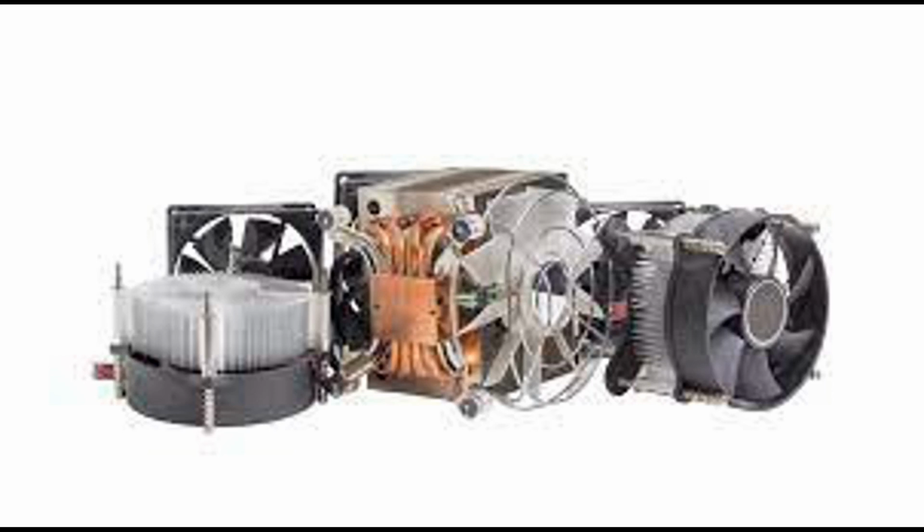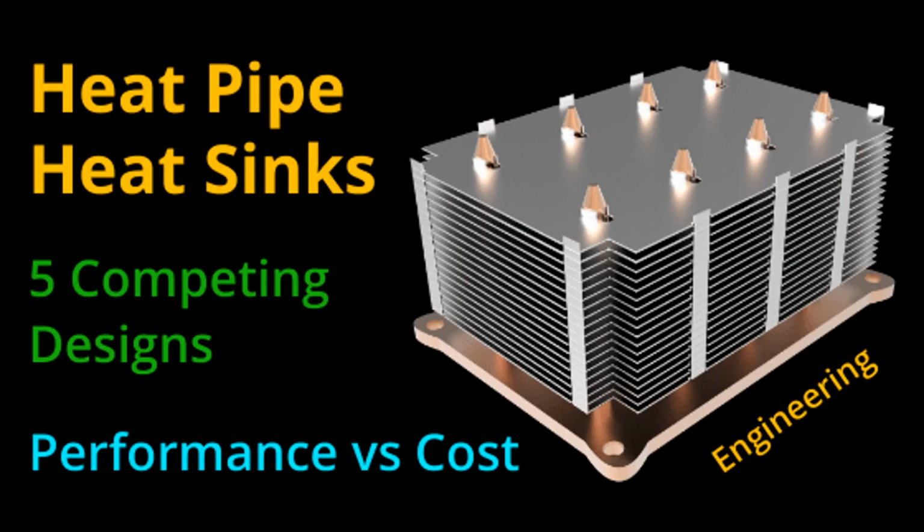Zigzag fin heat sink. Utilizes fins arranged in a zigzag pattern to increase surface area while maintaining structural integrity. This design is often used in compact electronic devices where space is limited. Swirl fin heat sink. Incorporates fins with a spiral or helical pattern to promote swirling airflow, which enhances heat transfer and dissipation efficiency. Finned heat sinks are commonly used in electronic devices and systems where passive cooling is sufficient to manage heat generated by components such as CPUs, GPUs, power transistors, and LED lights. They are versatile, cost-effective, and easy to install, making them a popular choice for thermal management in a wide range of applications.